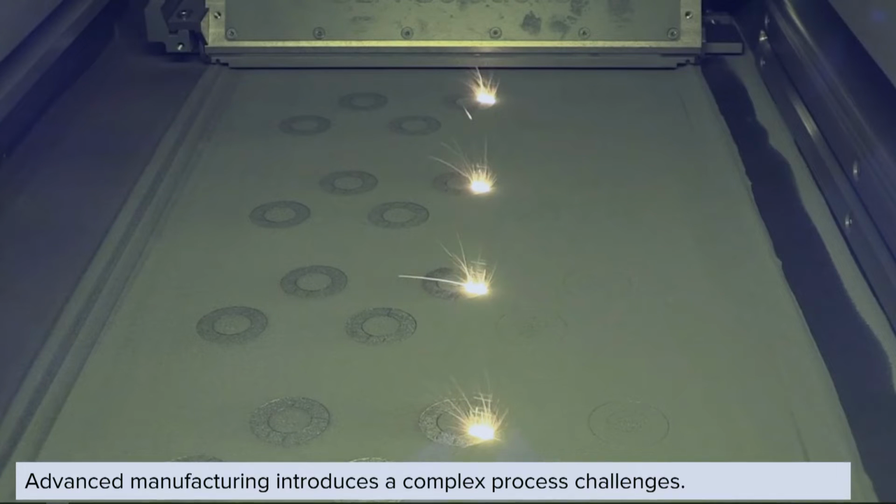You're going to find out that environmental factors can affect what you're doing. Humidity, for example, can make it so one day you produce a good part, the next day it has totally different properties because of a change like that. You wouldn't believe what can mess up these laminated objects. I can tell you a story of a company that bought a machine and they put it in an office building, and they noticed that every once in a while the layers were getting messed up. Just up the build, every once in a while, for a little while, the layers would be all messed up. And after a little while, they realized that that was happening during rush hour.